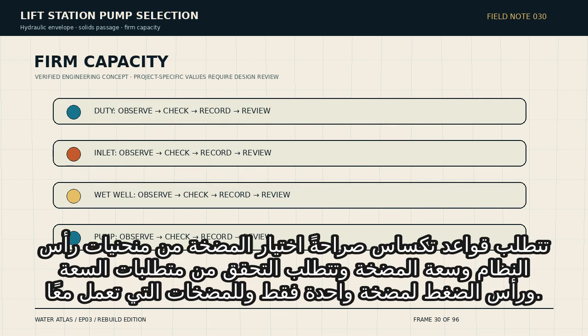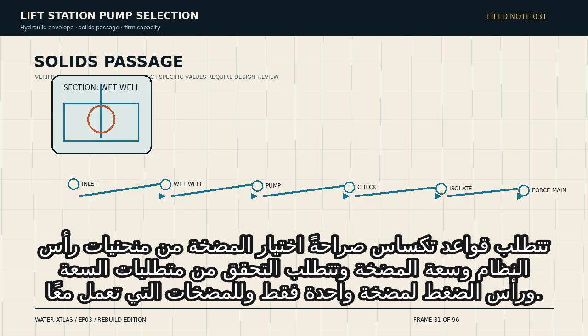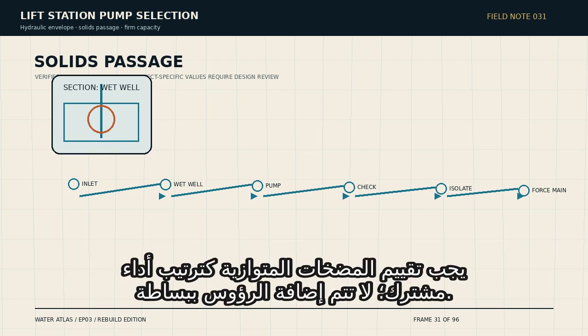The result is a transparent starting point. Define the flow envelope, build the system head cases, and then test whether the proposed pump configuration reaches the required operating points without hiding the assumptions that created them.